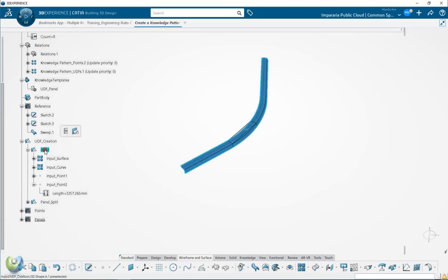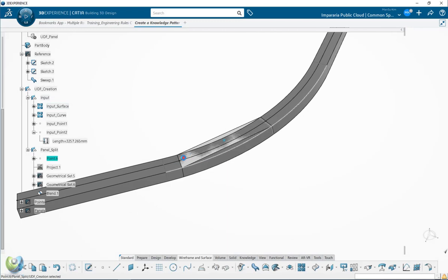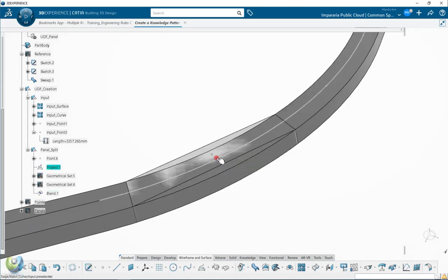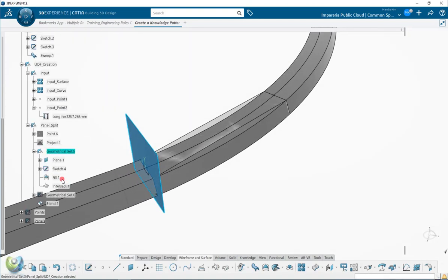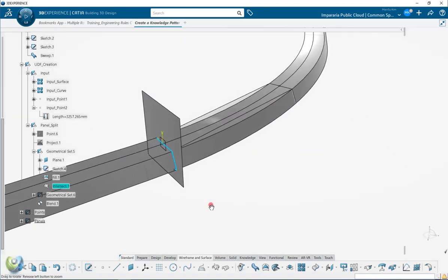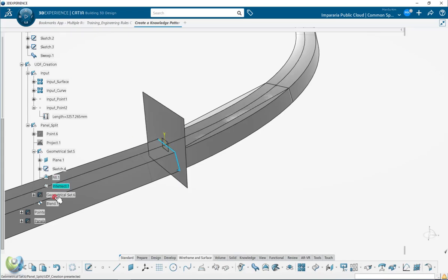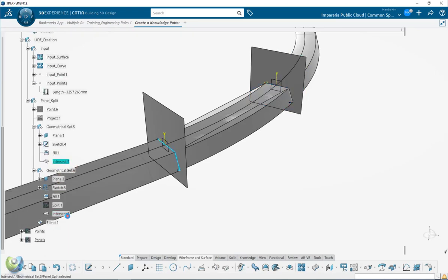So this is the input, and from the input we're creating, let's say from here, in the middle, an input curve. Then we can create the middle curve and project on the curve. Then from here, for each place, you can create a small surface for the intersect line between the surface and the face. Same thing for the ending point as well. Then now you have two intersection curves, and you can create the segment.